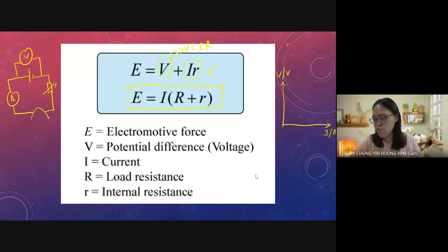OK, 东君讲 decrease, 苏君也是 decrease, others agree 吗? OK, 启瑞也是讲 decrease. OK, very good. Yes, it's decreasing. 因为你不要忘记, 它的 voltmeter 是 connected to battery. 你要明白, 讲说你 current 越高的话, 就是说它的 internal resistance in the battery 就会越高. 所以它 supply the voltage to move the charges across 的那个 circuit 会越高, 所以你的 voltmeter reading 在你的 battery 的就会越来越少. 所以你就会看到那个 graph 是一个 straight line graph diagonal 的.